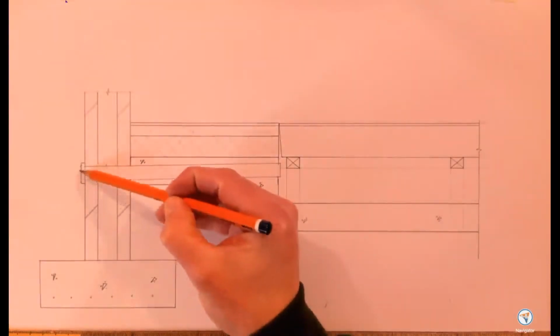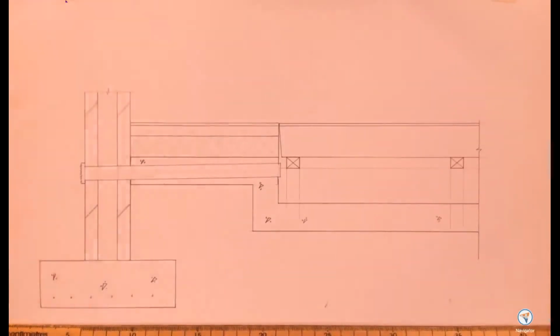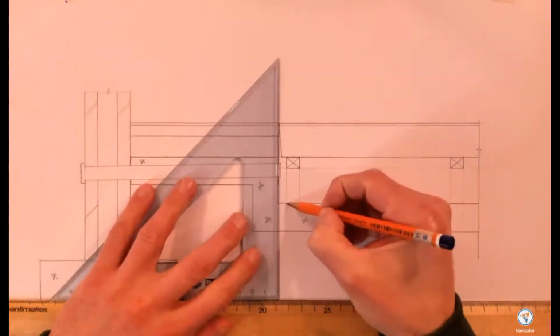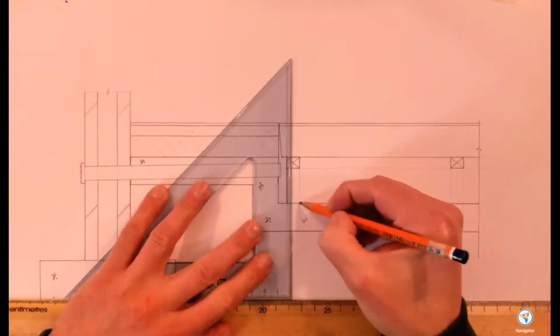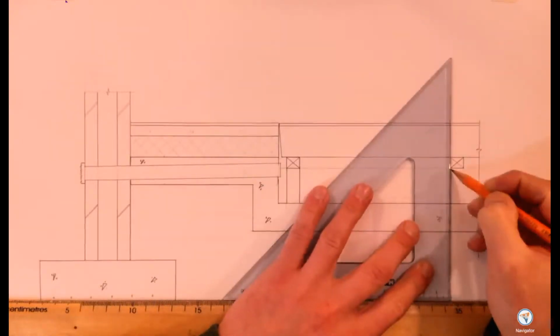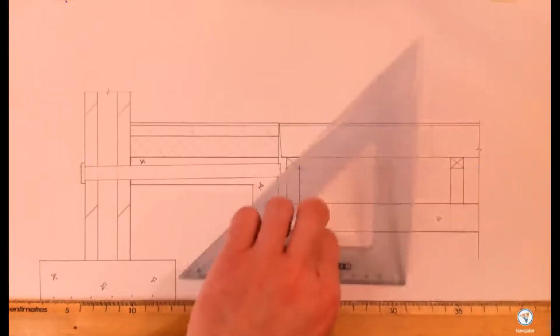I've put a vent onto the pipe just to stop any mice or insects or animals getting into it. We'll go finishing the detail on the drawing now. So at this stage we can put in our rising walls. So we've got the position of them put in. They're obviously directly underneath the wall plate. So these are our honeycombed walls, and they will let air in through them.